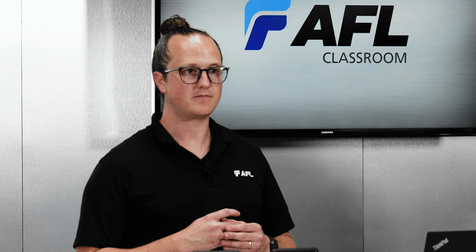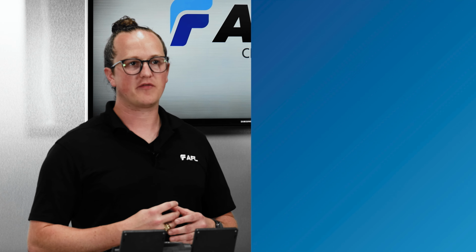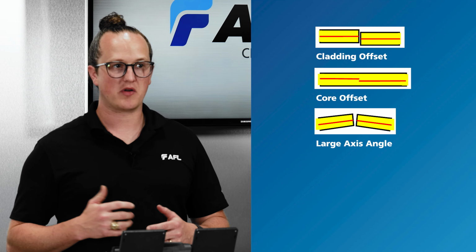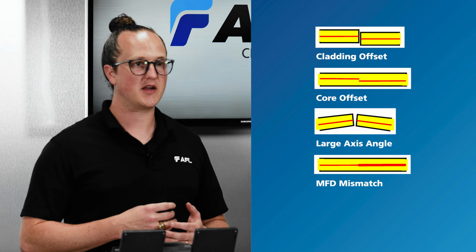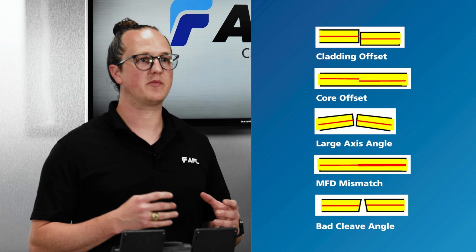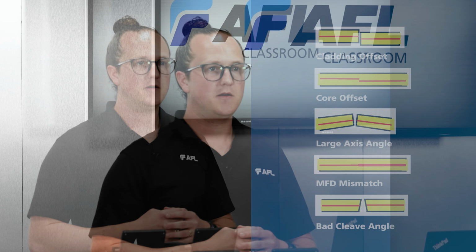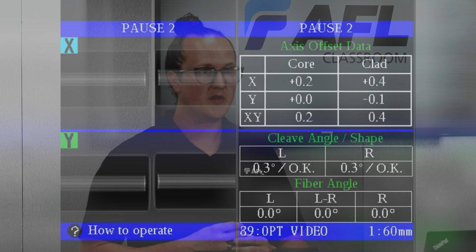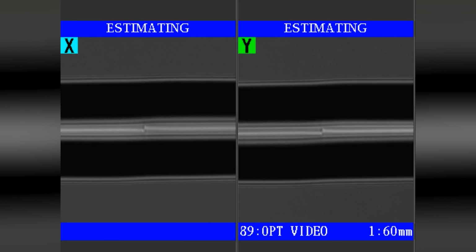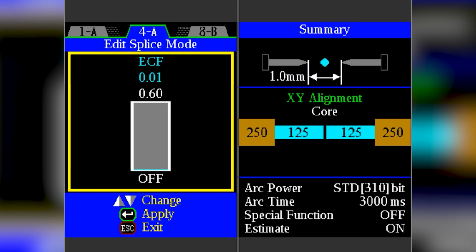during the splice. In the splice images, the main fiber-related conditions commonly observed are from splices with a cladding offset, a core offset, splices with a large fiber angle, mode field diameter mismatch, or splices with a large cleave angle. Each one of these has a unique presentation, but on a high level, here are some quick diagnoses for each of these. When fibers are spliced with a cladding offset, usually you'll see some core deformation or core smearing at the splice point. Correct this by experimenting with the eccentricity correction function, or ECF value, to minimize core deformation at